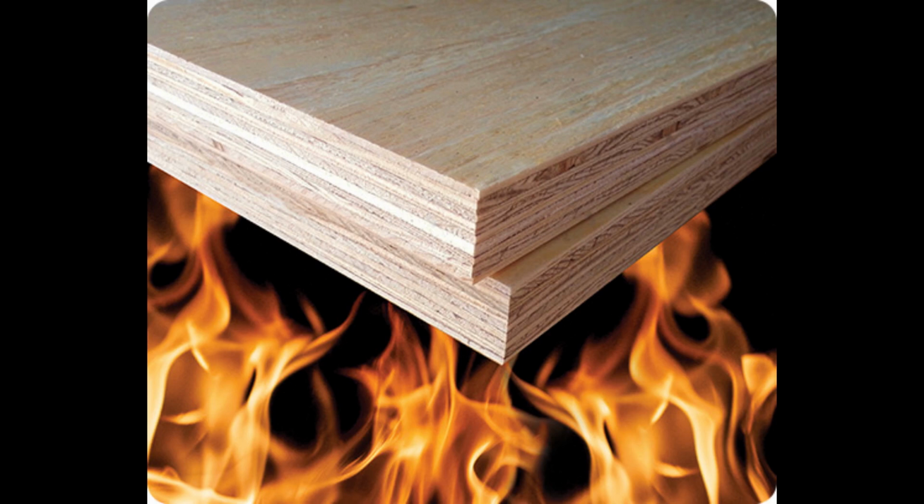Baltic birch plywood is a product of an area around the Baltic Sea. Originally manufactured for European cabinet makers but now popular in the US as well. It is composed of an inner void free core of cross banded birch plies with an exterior grade adhesive. The face veneers are thicker than traditional cabinet grade.